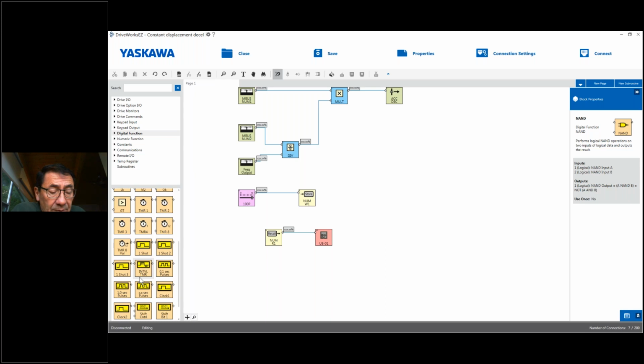Now, in the actual application, we'll need to make sure that our velocity as we go by the prox is not so fast that the prox pulse that the program sees is shorter than the read time of the program. We can make that pulse longer by making the target longer, for example, because we don't want to have to slow down just to accommodate the read rate of the program. So we could use a bigger piece of metal, and then the prox is on longer as we go by it. But we just need to make sure that that detail is accounted for in our engineering.